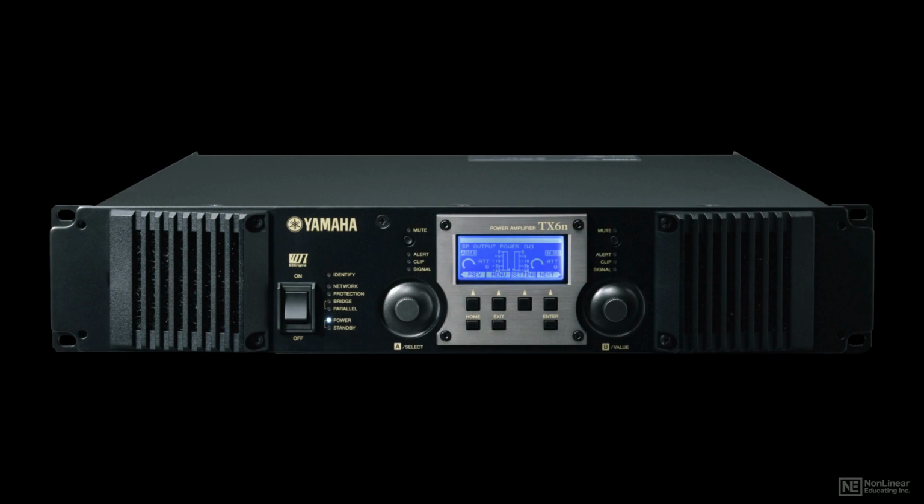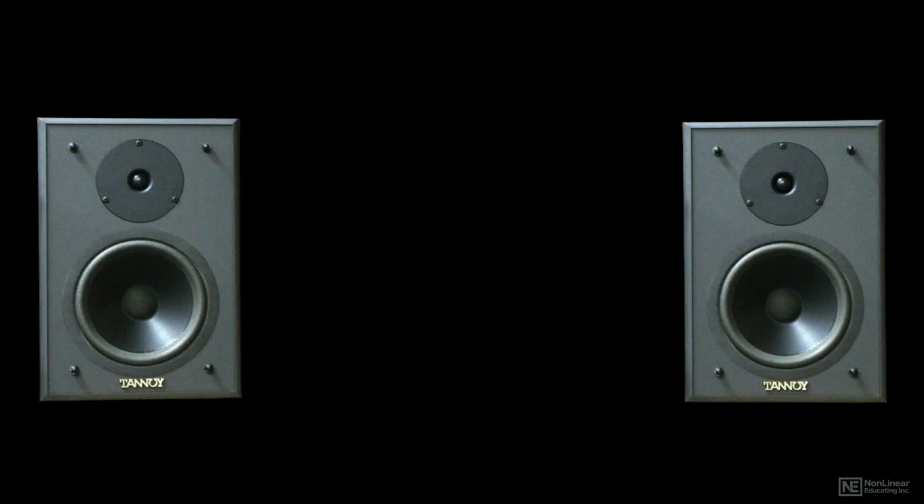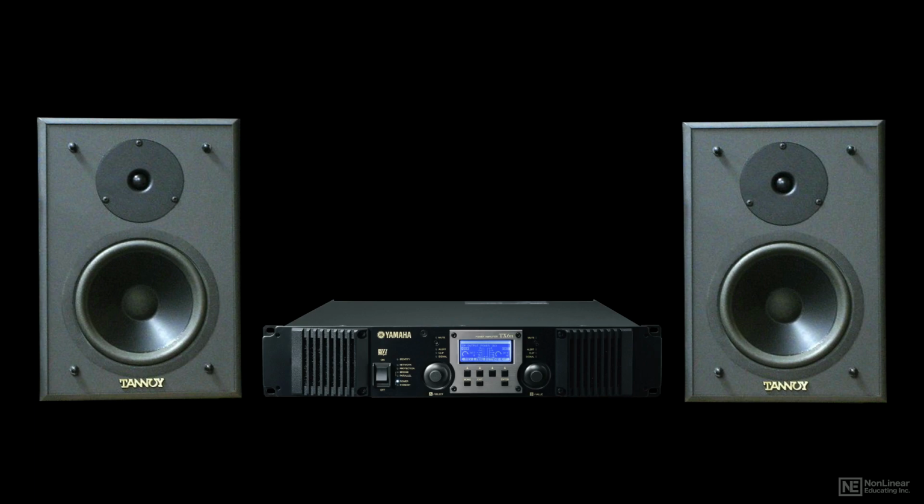But when most people use the term amplifier or amp, they're referring to a power amp. Analog audio signals passing through a console or interface are usually represented as voltages. This is the most efficient approach. But when it comes time to push a heavy speaker back and forth to create the acoustic sound wave for monitoring, voltage is converted to current to power, and this is where the power amp comes in.